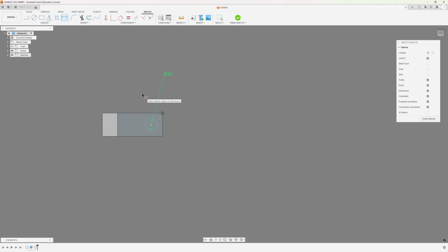tap on there that I'm going to be drilling, because a lot of times I've seen a lot of engineering students or engineers themselves spec out a 7/16, like for this 7/16 20 hole, and they will then put a 7/16 hole into the part, which is absolutely wrong, because your 7/16 hole is going to be oversized for a 7/16 bolt, because you need to go with the tap drill size. So for machining purposes, since I am a machinist and not an engineer, I always like to put my through hole as my tap drill size.